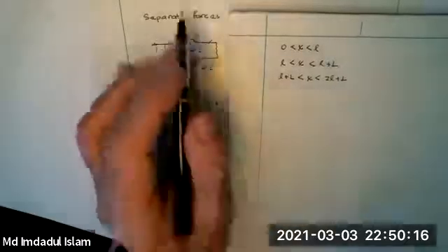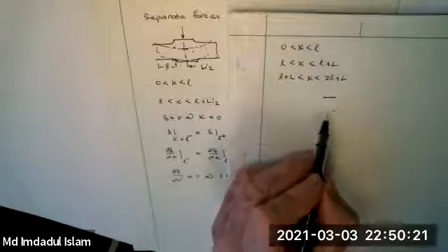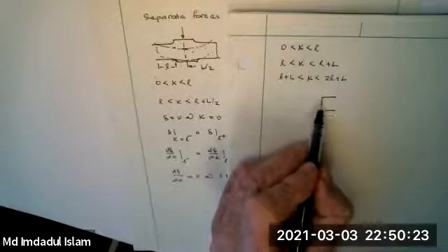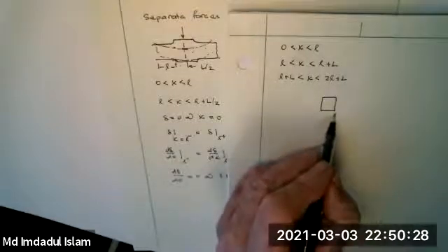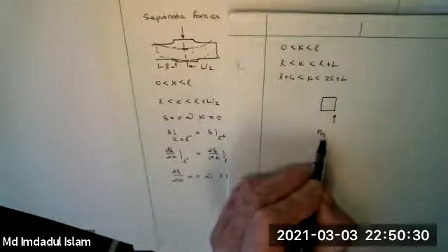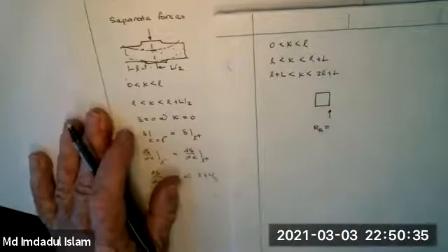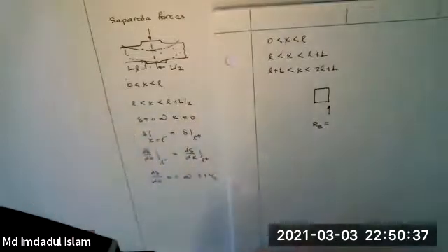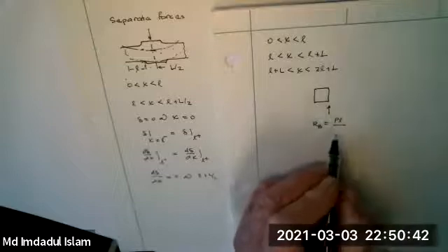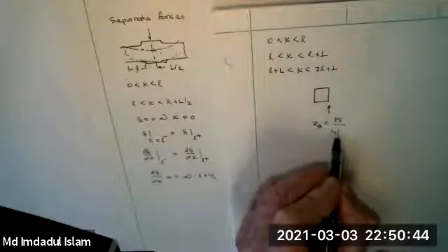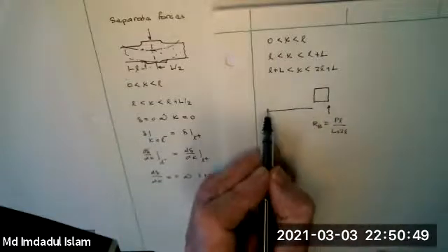And when you're doing the bending moment here, if you do it from the end, then like this, here you have RB, which we solved for using statics. As far as P was concerned, this distance is X.